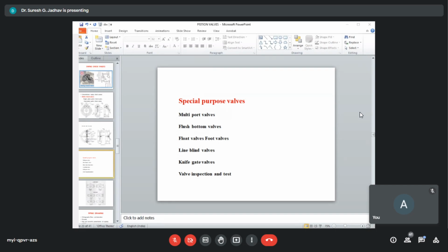Now the next kind of valve is the foot valve. Foot valves are a sort of non-return valve with strainers mounted at the open end of the pump suction lines. These are used when the pump has negative suction. The check action of the valve holds the priming fluid of the pump while the pumps are filled before starting. The suction strainer helps to hold back solids while the pump is sucking the fluid.